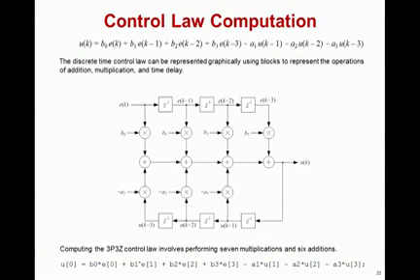Taking this equation, we can actually represent it using a state or block diagram shown here. Across the top of the diagram, you see a time delay of 1 to result in e(k-1), another time delay to result in e(k-2), and a third time delay to result in e(k-3). Each of these delayed samples is then multiplied and added together to equate to the output shown in the equation.